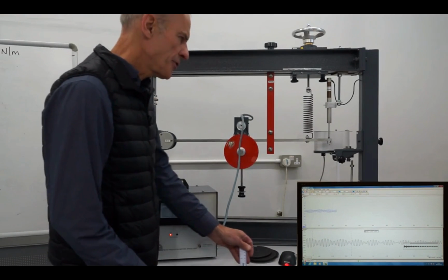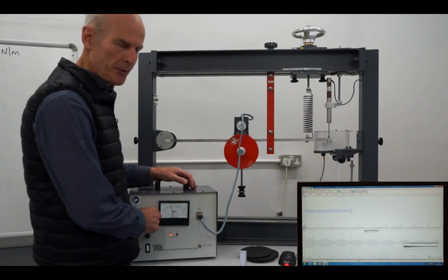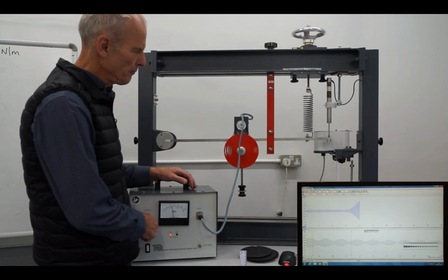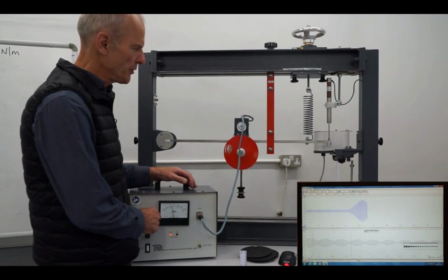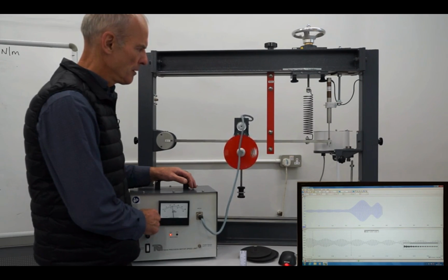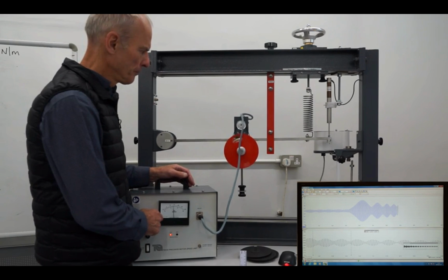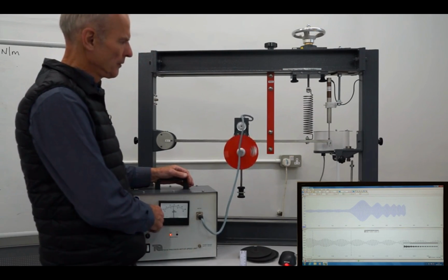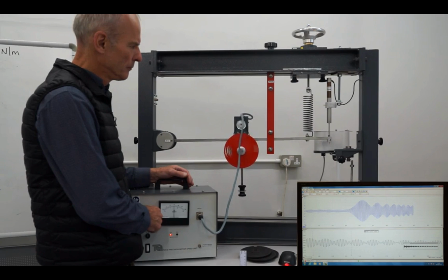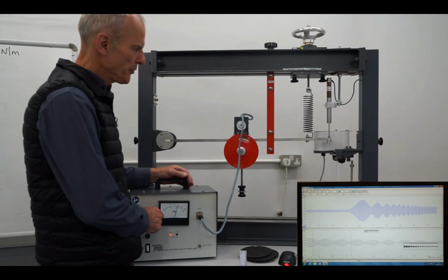If we actually increase the frequency from this, this should be close to resonance. If we increase it a bit, which is what I'm doing now, you can see that we're really getting large amplitude vibrations, and this is basically something to be avoided. And if we're not careful, it would actually damage the system. And if we increase this beyond resonance to a very high frequency, then you can see that the vibrations start to go down a little bit.